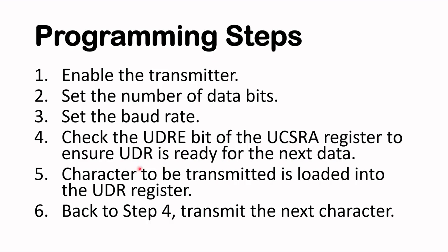Then the character to be transmitted, that means the character that you want to send out, you have to load it into the UDR register. And then if you are sending more than one character, you go back to step 4 and repeat this until the message or the number of characters that you want to send is complete.